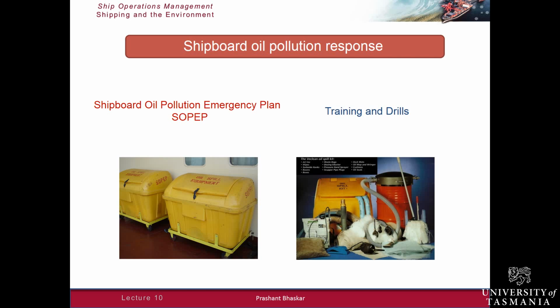MARPOL also requires a shipboard oil pollution emergency plan, or SOPEP, to be established. And basically, the SOPEP would include a procedure that would be followed by the ship's crew to report an oil pollution incident, a list of persons or authorities to contact, a detailed action plan to be taken up by the ship's crew to reduce and control the discharge of oil, and designated procedures and point of contact for coordinating shipboard action with both local as well as national authorities in combating the pollution.